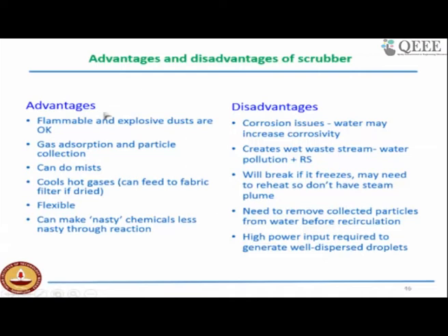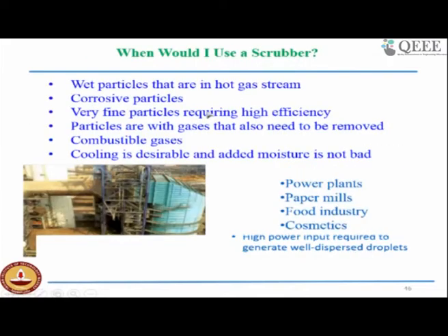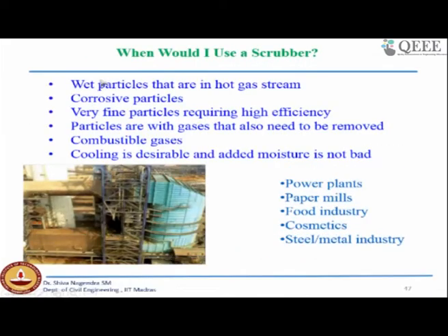Scrubbing, as you know, is best exemplified by raindrops removing the particles in the urban environment. The finer the droplets, the more particles will get removed, and that's why you need finer drops in the scrubber design. So you need to understand the liquid flow rate and the flow rate of the gas. Accordingly, you can design the droplet dimensions or sizes. So you can use the scrubber.